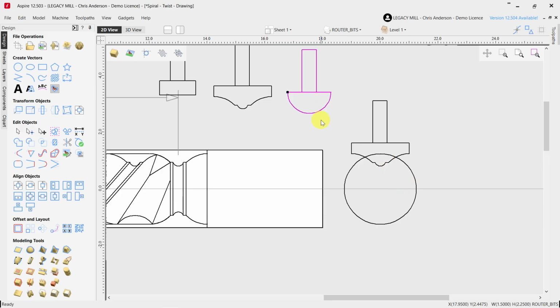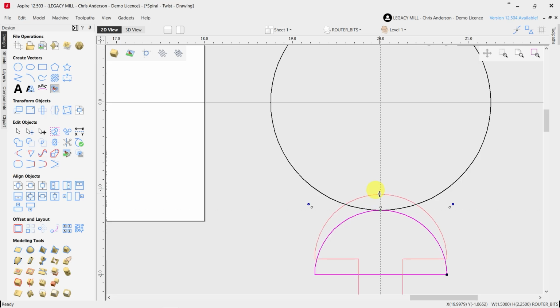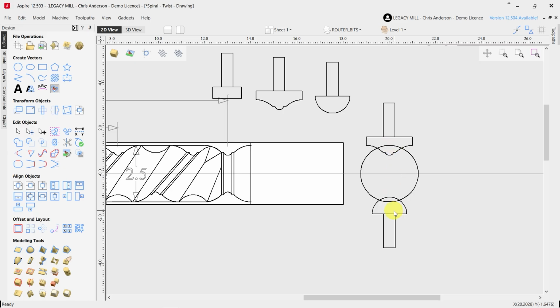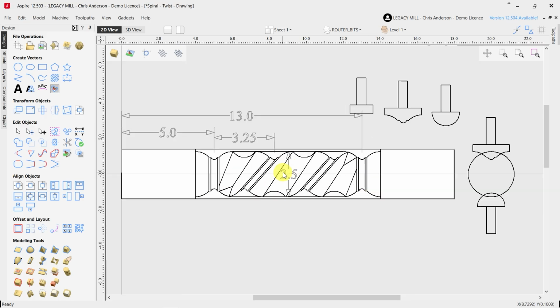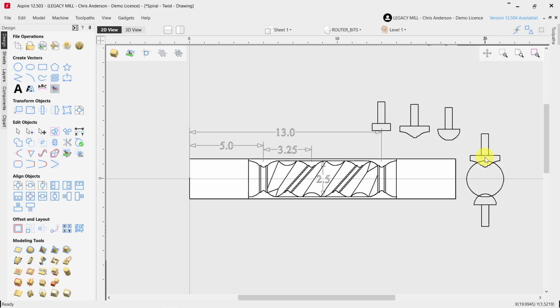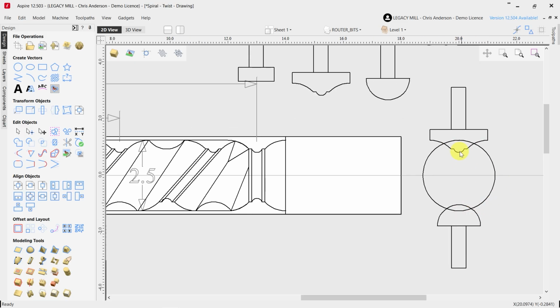And then the core box cutter, I'm just going to copy this. This is going to be on the opposite side. Okay, again, cutting right here, but that's going to be cutting a certain plunge depth as well, giving us that core box shape. And so these two cuts are on opposite sides of one another when cutting on the blank, but again, spiraling around one another. Okay? So think of it that way. It's pretty much a two-start spiral, but we programmed one separately, and we're going to program the other one separately so that we can select different cutters for those two starts.